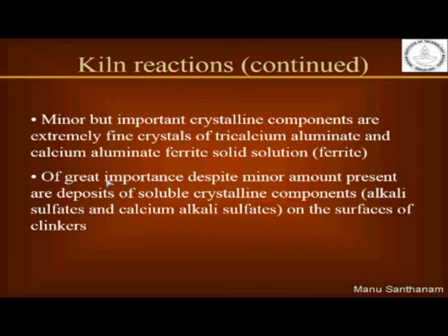That is why earlier I had said that C3S is a pure form, whereas alite is an impure form of C3S. So, when the alkalis and sulfates are present on the surface of these clinker particles, then they are called alite particles and not C3S particles.